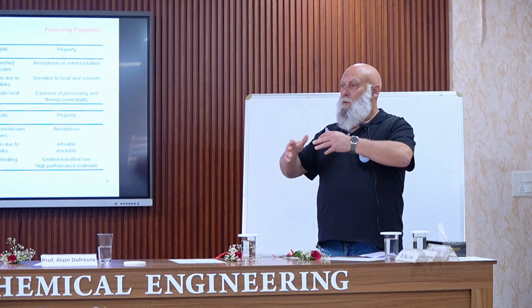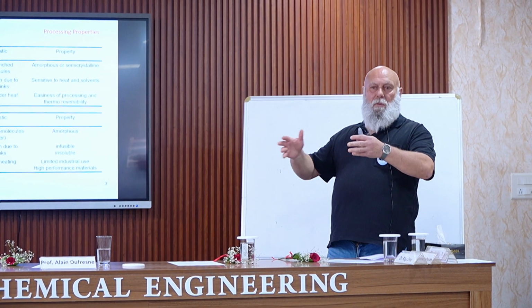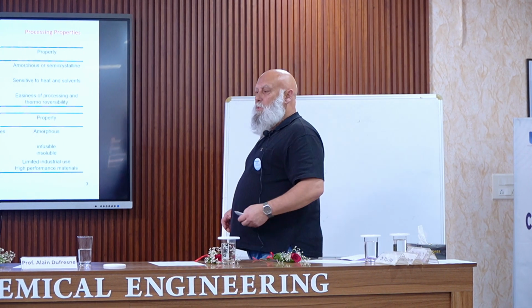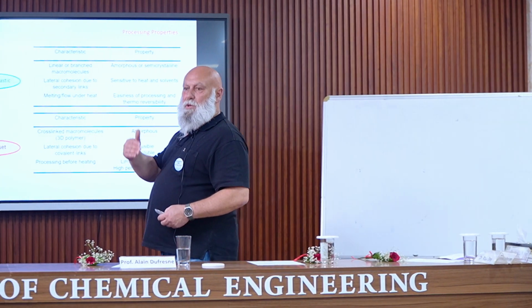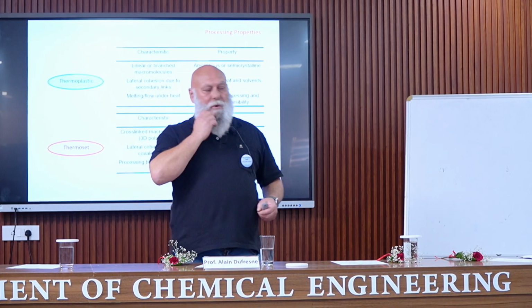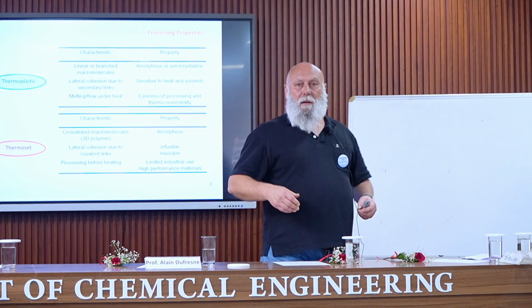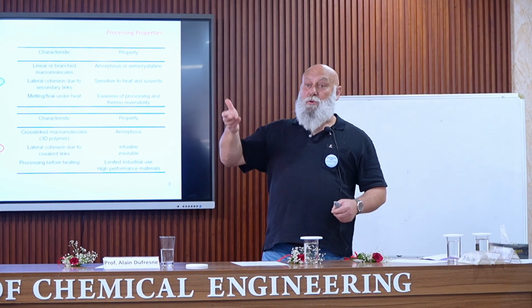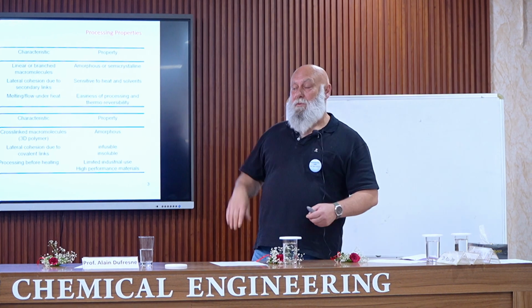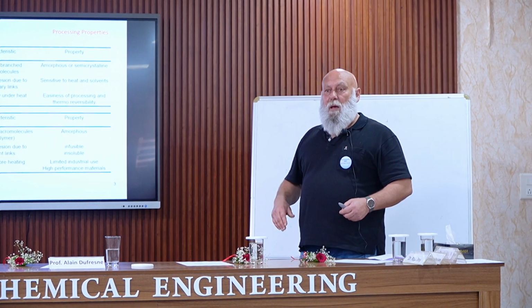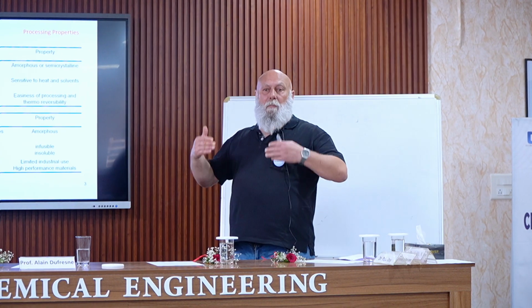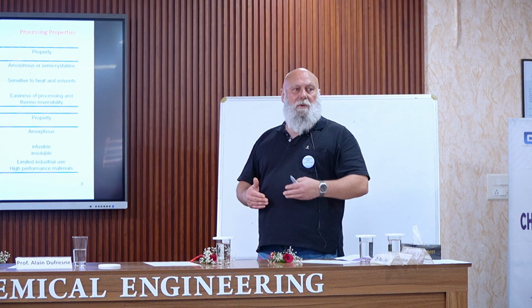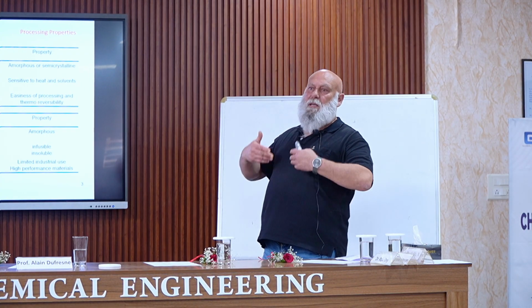So meaning that you can increase the temperature, give a different shape to the material, and by cooling fix this shape. In fact, it's not possible to make this process several times because during processing, shear forces are applied to the material and the temperature is also increased. And this process progressively degrades the polymer, meaning that the molecular weight decreases. So it means that this kind of thermoreversibility is possible, but only a few times.